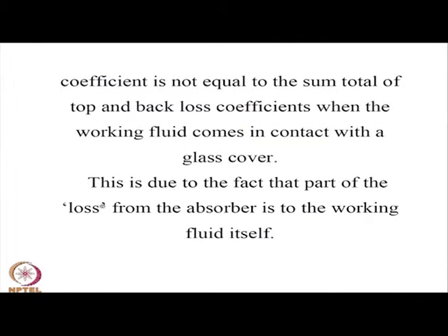So, this is what we had discussed in detail. The top loss coefficient will not be the overall loss coefficient if the heat transfer fluid comes in direct contact with the heat losing surface, as in this case, because apparently the loss from the absorber also goes to the fluid, which is the useful energy gain.